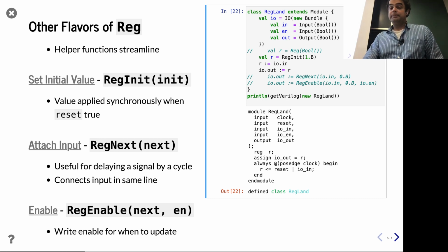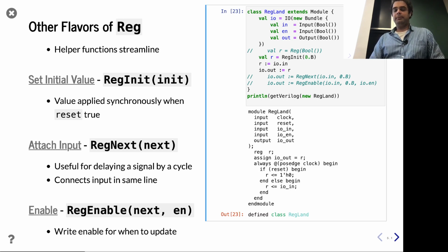Another thing to point out is that sometimes when you do things in the Chisel or FIRRTL tools, before you emit the Verilog, even if the Verilog seems not perfectly optimal, remember that the Verilog-based tool, whatever your CAD tool is, is also going to optimize things too. And so one of my core themes, of course, is let the tools do the work. In this case, if a human sat around thinking for a while, maybe you could think of this optimization, but you know what, the tools did it on their own, and that's great. My job is to make correct and clear hardware and then let the tools do the work, right? And so yeah, okay, cool. So that's us doing it with an initial value, but of course we can set it back to 0, no problem.